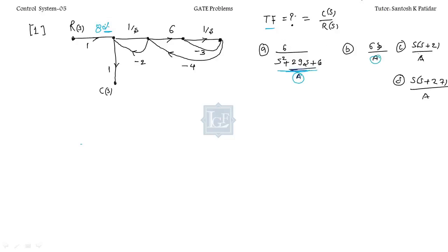So over here, the same value is given. Okay. So let's find the transfer function. Find out the forward path first. The forward path P1. You have to go to output C(s), and you will start your journey at the input level. So this is the forward path you are getting.